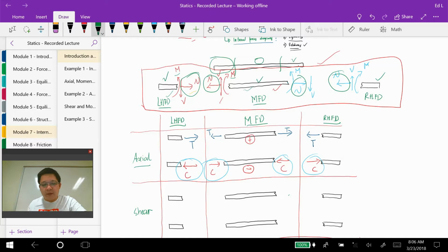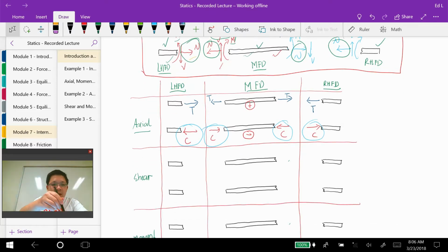Okay, right, then let's look at shear. The positive sign convention that we agree on for shear is derived based on the middle free body diagram, so it's similar to the axial force. We have a positive shear if the couple that occurs at the middle free body diagram produces a clockwise moment.